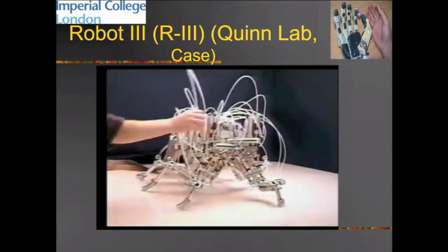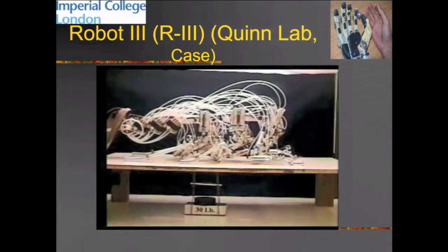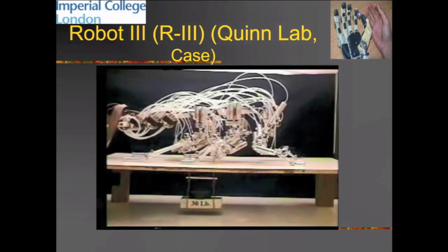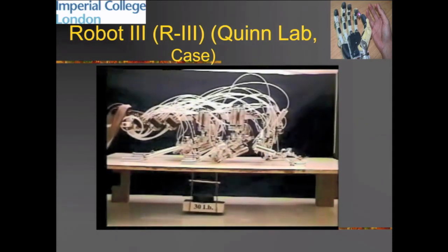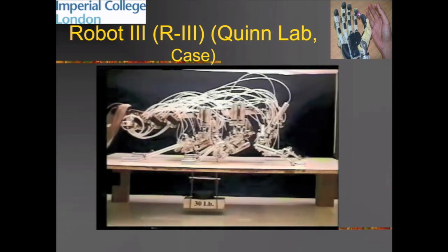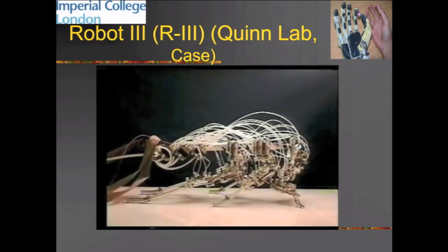In this case, there was a 24-degree of freedom Lagrangian model, and it's all done with pneumatic cylinders. The pneumatic cylinders are trying to capture some compliance akin to muscle compliance. So if you saw it bouncing up and down like that, imagine if it was walking over a surface that was kind of shaking. That's a posture controller.